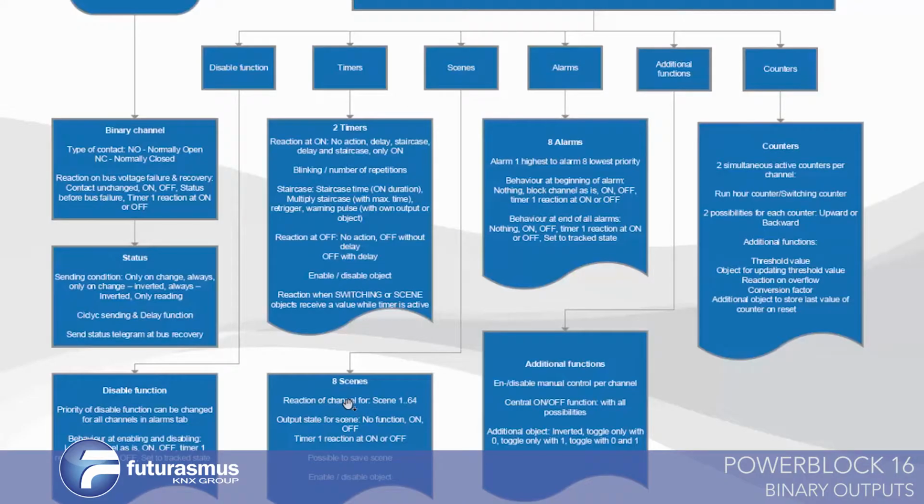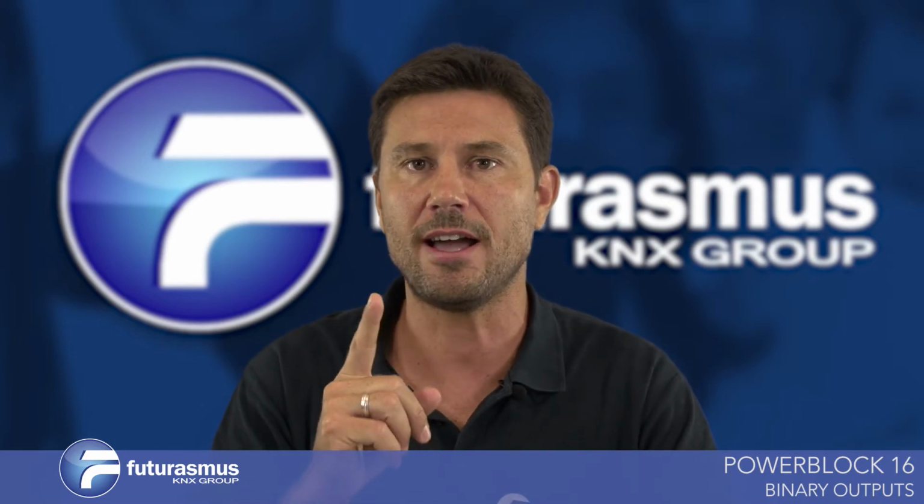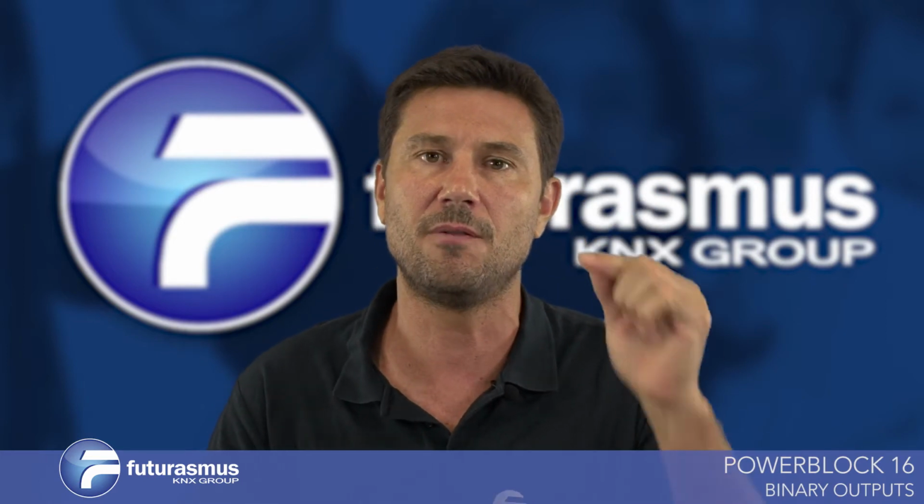Additionally to those scene modules, we've got the normal KNX 8-bit scene object, and which is also very important, there's one scene object per output. So actually you have much more possibilities than having only one scene object for the whole actuator. So you've got one scene object per output, which you can set so that if scene 1 comes, the output is on. If scene 2 comes, the output is off, and so on.